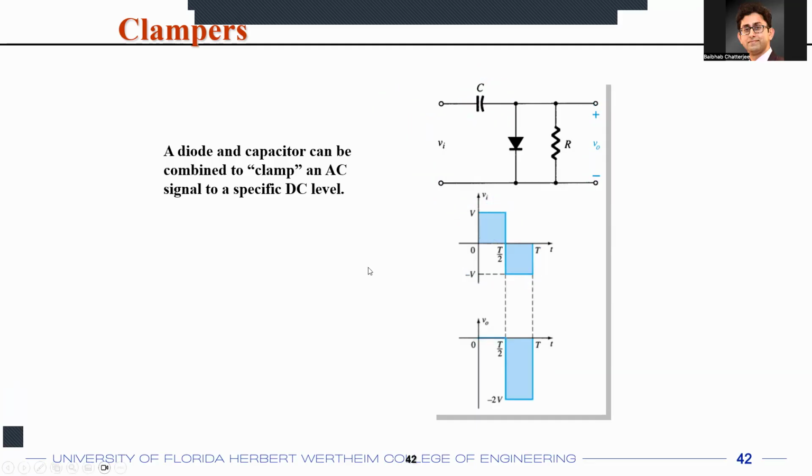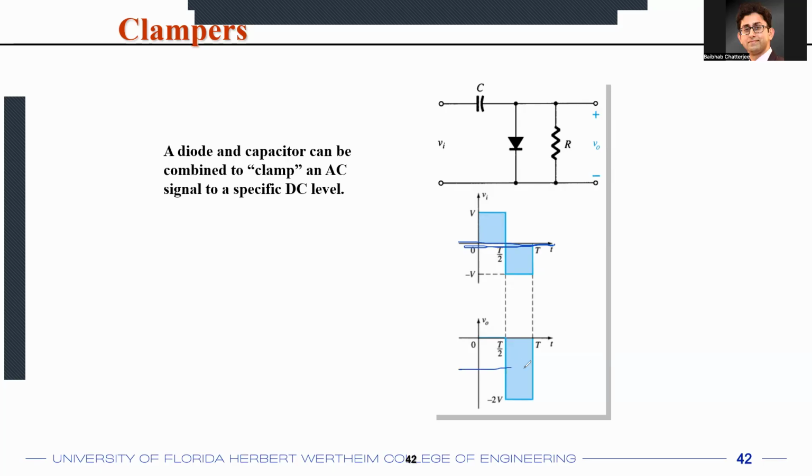And this is called a clamping circuit because what you are effectively doing is clamping the DC point. So for example, this was your DC biasing point initially, or the common mode voltage. So you're clamping the common mode voltage to some other voltage value, which is over here. It's the same square wave, still going up and down like this, but around a different DC voltage or different common mode voltage, because everything has been pushed down by 1 Vm.